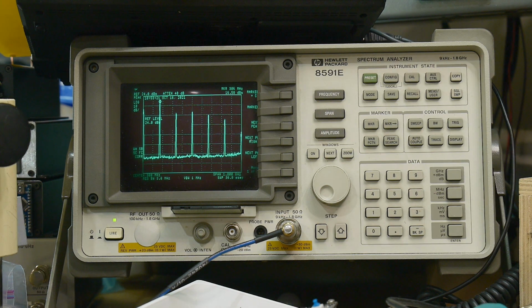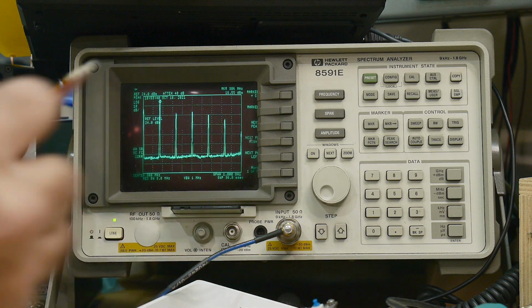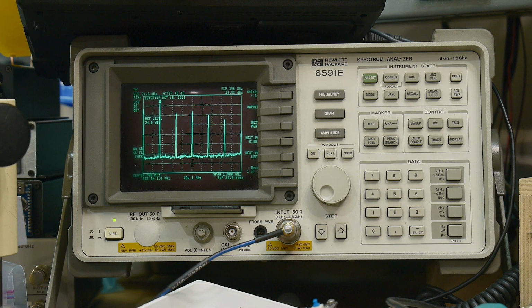That's enough to blow up this TinySA. Good thing this SA can handle it. This thing can handle that much power. Let's see. What is the? I think it's plus 20, plus 30. Yeah, this thing will go up to plus 30. But if you were running the same thing into another spectrum analyzer, you could have blown it up already. So really be worried about that. Really should put a pad on this thing.